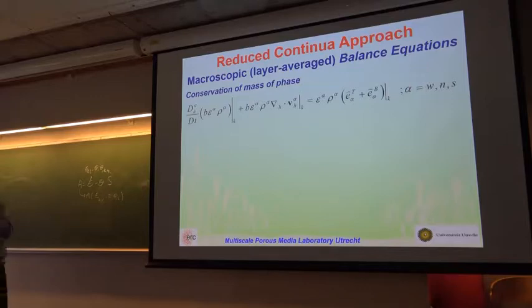But I'm trying to say, if you have water and compressible as mass density is constant, then I like to work with mass of water per volume of water. Well, whatever you say, but basically for transport on two-dimensional surfaces, you use properties per unit of surface area. And here this is the volume of the phase per volume of the layer. But I don't see what additional benefit it gives me. If I have mass of water per volume of water, why should I make it per surface area? Since you average over the thickness of the layer, what you basically get is the integral of the property over the layer. Now, since that property is per unit of volume, after you integrate it, it's per unit of surface area.